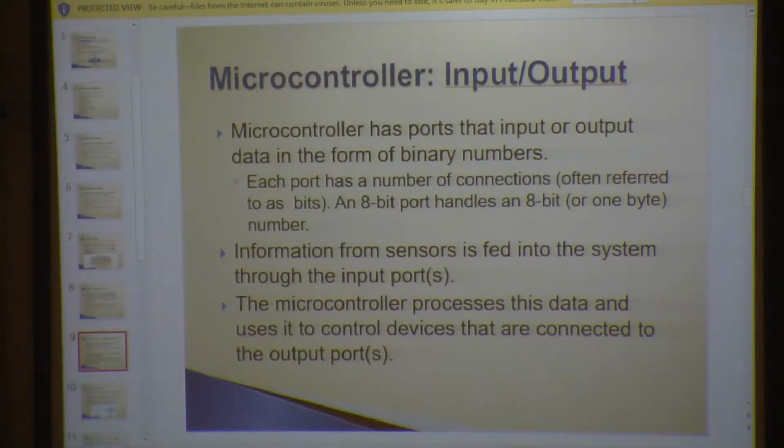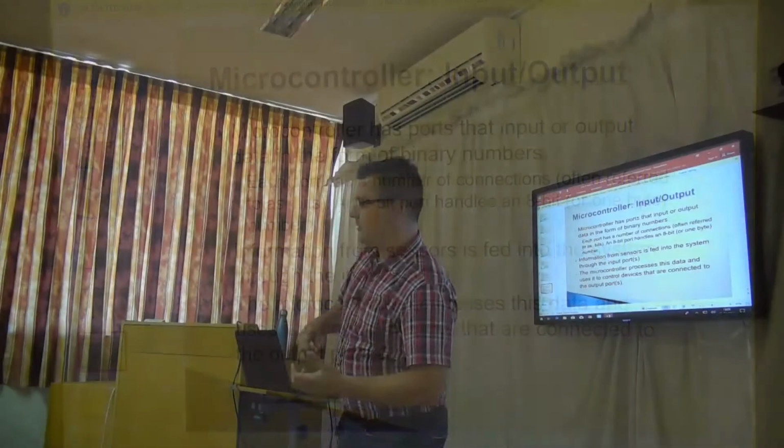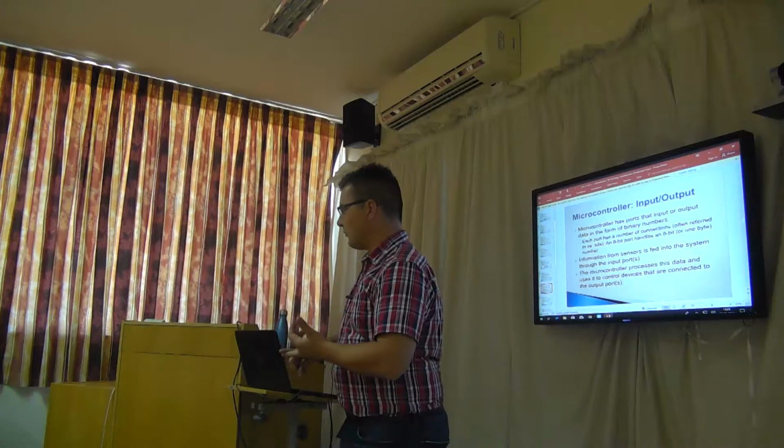Okay. So, as I was saying, we have inputs and we have outputs on a microcontroller that can either take in analog or digital data. Even on your output, you can output analog values in terms of pulse width modulated data. Then it generates an analog wave through pulses, but it can also do digital values for you, 0 or 1, on or off.